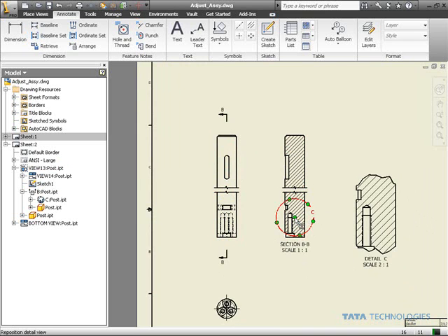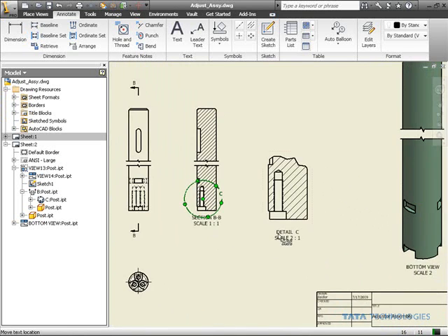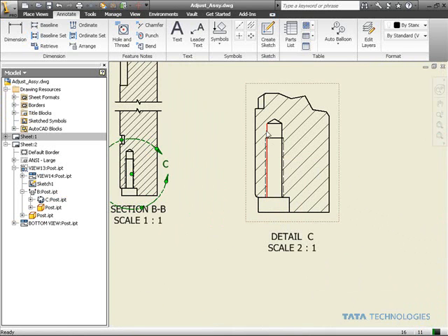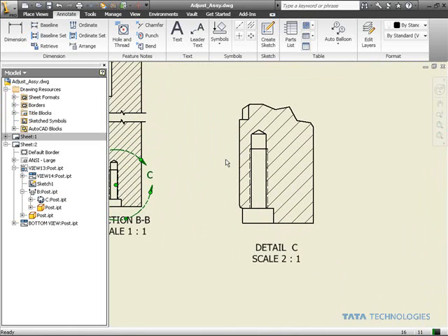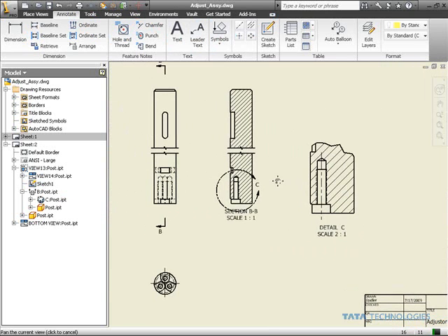Let's go ahead and add a center line to our chamfered hole here. So with our annotate tool, we have our centerline bisector. So let's click on our chamfered hole and then clean up. So that's your centerline bisector, and we can also add center marks.